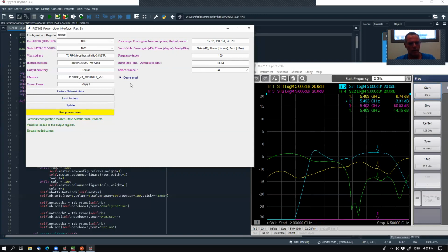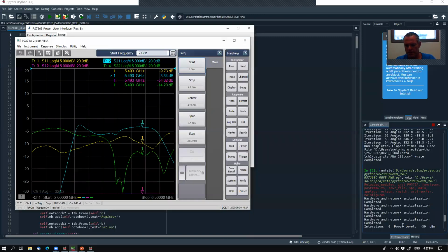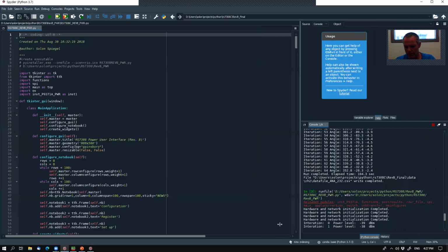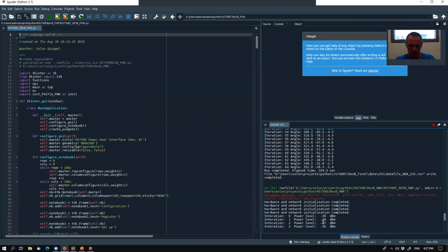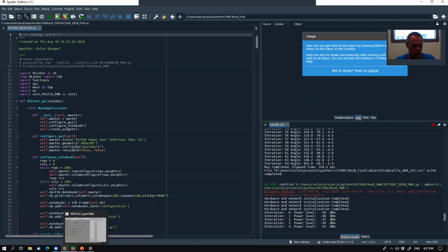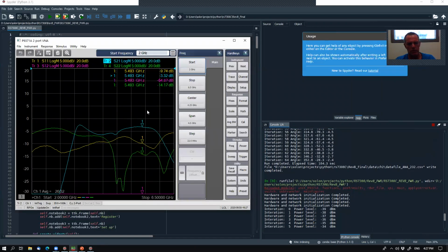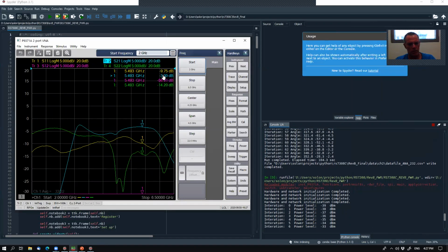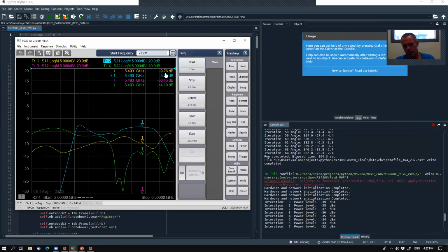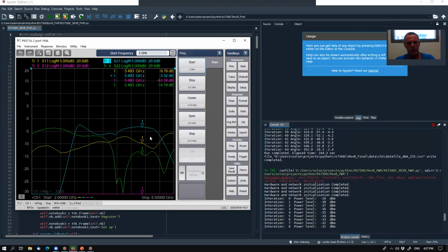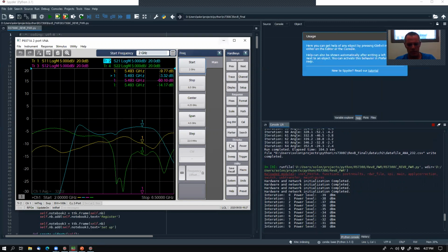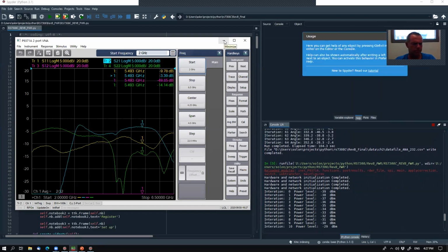One update. And then here, if you want to create Excel, that's going to create an Excel immediately. So let's run power sweep. So we're going to apply run power sweep. And the same thing you see here. And start the interaction, -40. And let's look at the network analyzer, for example. It's not changing, the power is small, so there's no effect of compression. So this is the sweep.